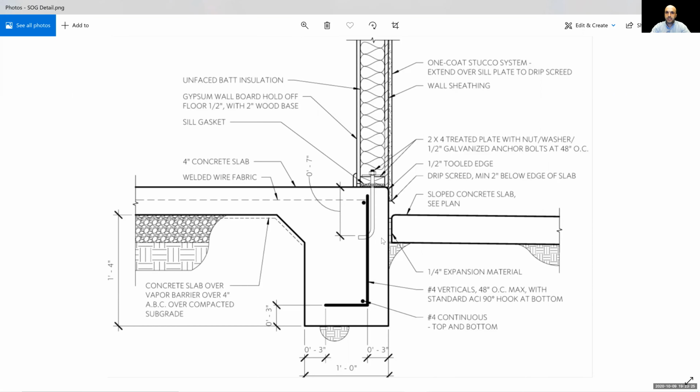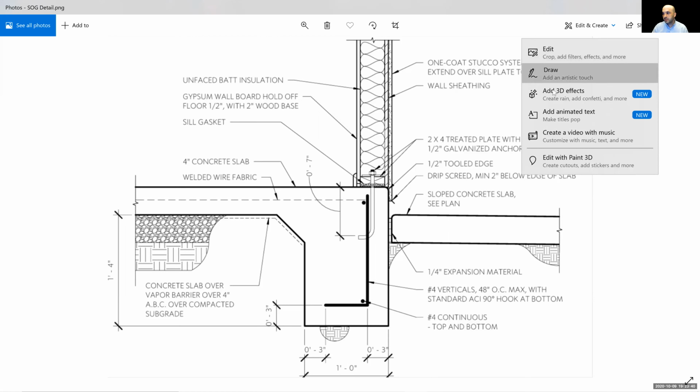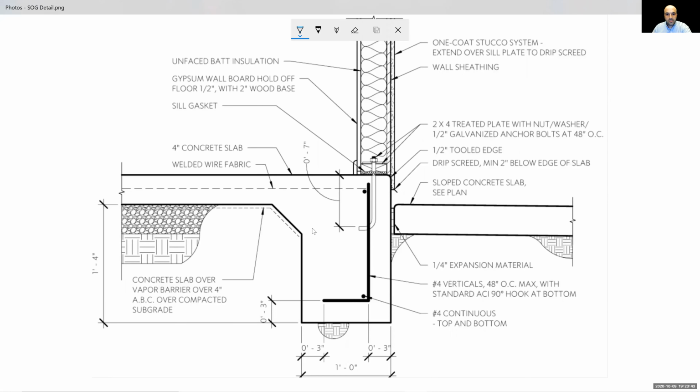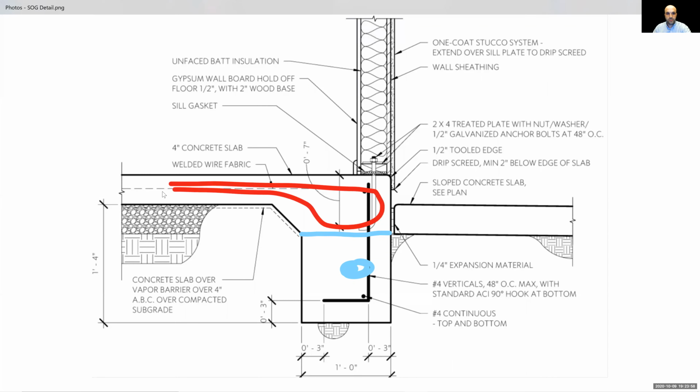However, on the construction side of things, we're bridging both worlds, remember, that won't be poured at the same time. At least, different subcontractors will do it differently, but from what I've seen, or the times that I've been involved, this will be poured like so. This part goes in first, and then after however long, they come in and they pour the rest of this, right? So we could model this in two elements, right? We could model a floor and then just one slab edge. That is a tool that exists in Revit.